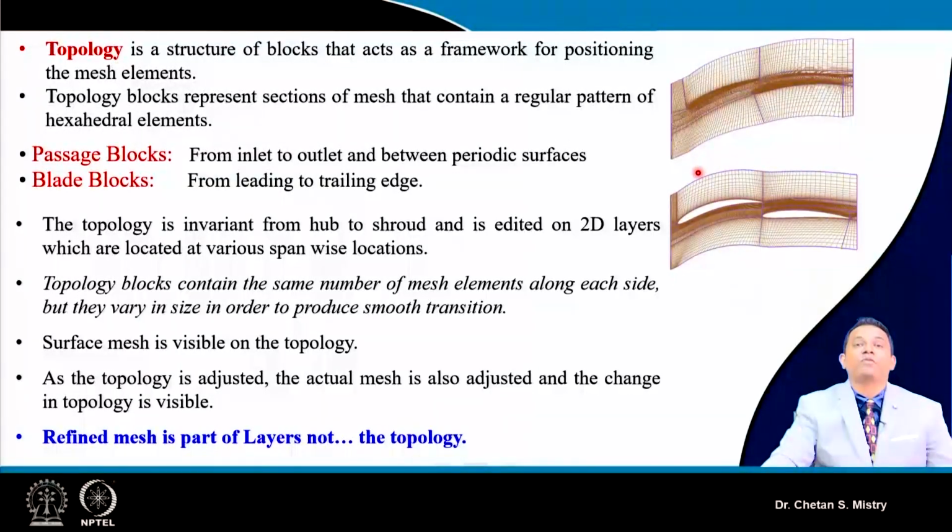Whatever tool we are using, we need a thorough understanding. Suppose this is one of the challenging aspects, the tandem bladed rotor, which we were also discussing in week 3. In this case, my interest is in what flow happens near my leading edge, the leading edge of my second blade, and the trailing edge, or exit, of my first rotor blade.